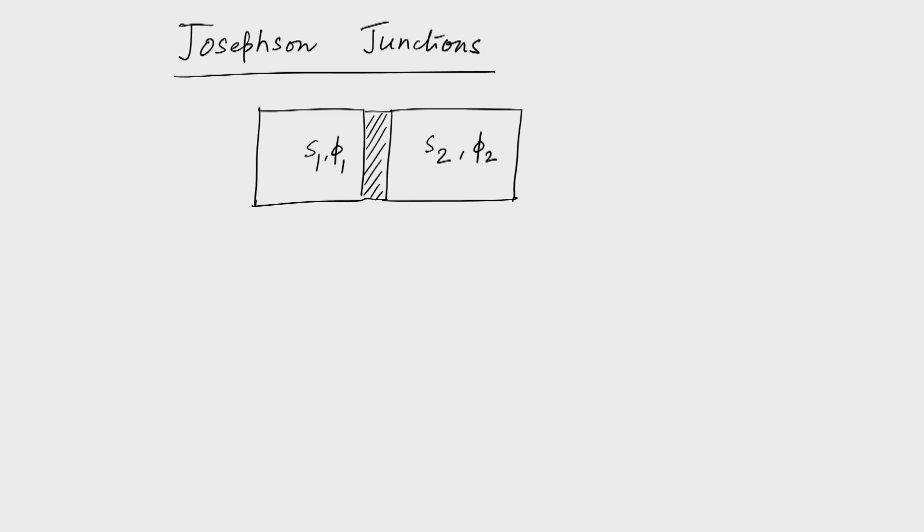A current actually flows through this, and this is called the Josephson current, and this junction is called the Josephson junction. And as I said, just the way transistors are important to semiconductor electronics, these Josephson junctions lie at the heart of superconductor based electronics. Strictly speaking, the resistance-less current that flows, which is a Josephson current, is a manifestation of the DC Josephson effect.